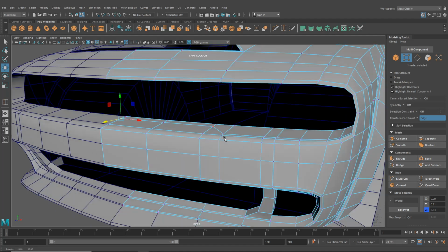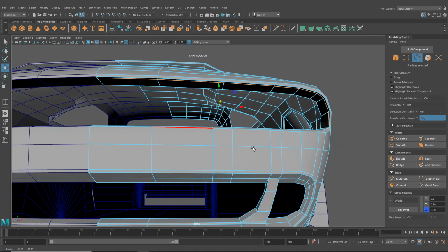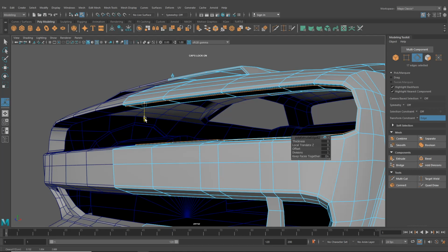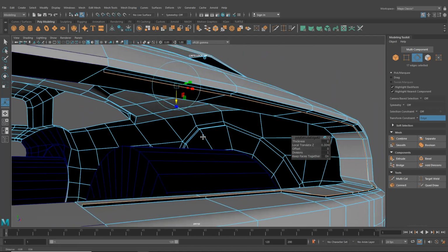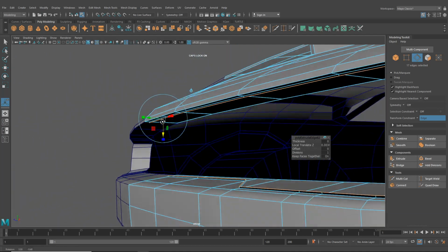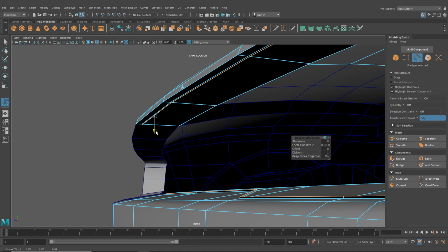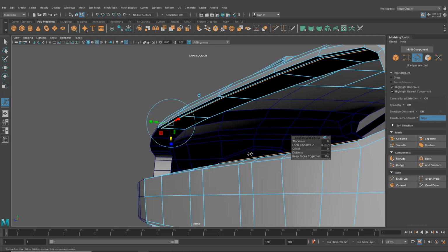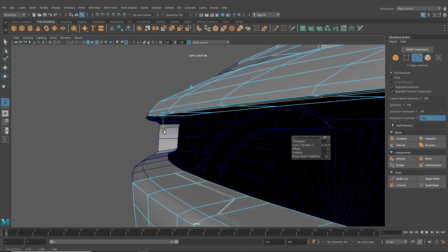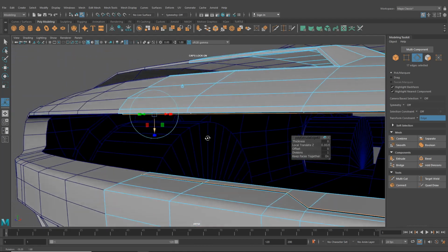So what we can do now with this is let's grab those edges again. I'm going to hit Control E, and then on the blue here, I'm just going to pull it in ever so slightly. Something like that, that should be okay. Because obviously we're working with a 3D model here, so we do need to exaggerate things a little bit to make sure we get good contrast. And again, once this is smoothed, it'll lose a little bit of that width too. So we'll take that in.